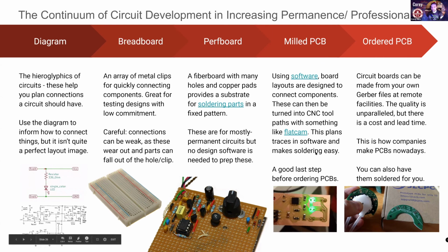So this is something that we can totally work on, but just knowing that this progression exists and how I would relate these 5 steps together is relatively useful to see where you're going. If your Arduino projects live in the perf board space, you're totally good. I would caution you against stopping a project in a breadboard place, because the connections do get weaker over time and your project will fall apart. You definitely want to transition to perf board if you want to keep it around for more than a couple of days, because the breadboards do just wear out. So you want to make sure that you get to this point.